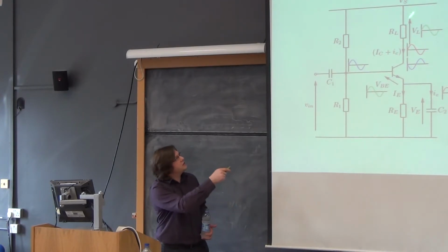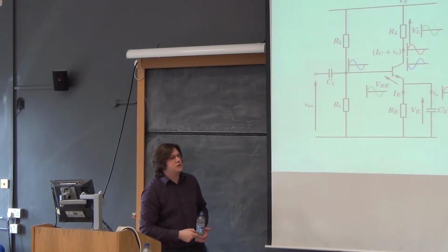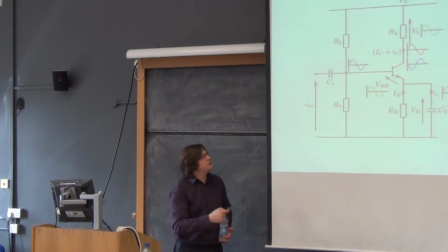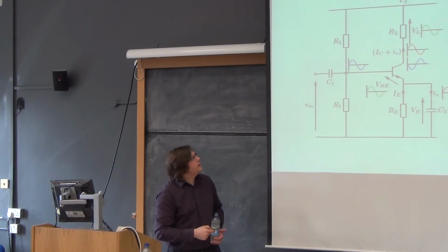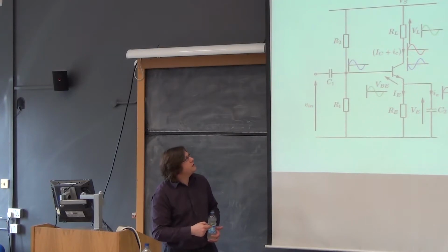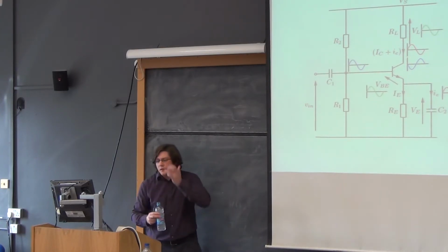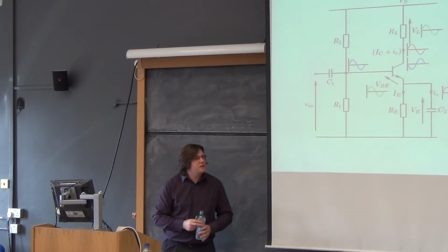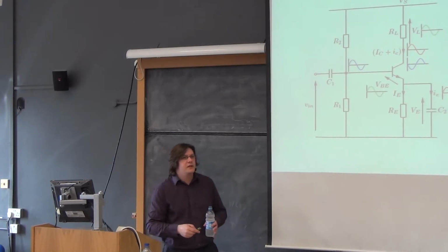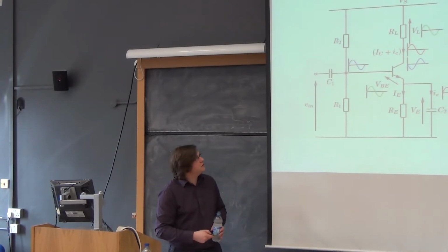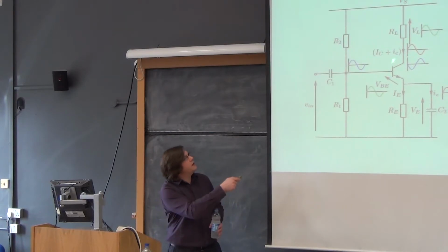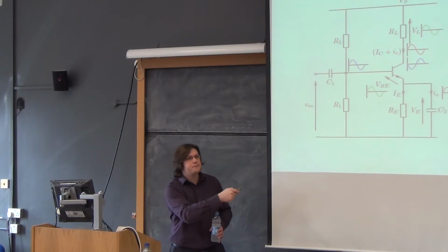This is the quiescent current that sets up all those voltages for us. Well, most of them. And we have to make sure that there is sufficient feedback at DC to keep stability in those values, because let's just say I had 2 milliamps as big IC, and there were no signals at all.